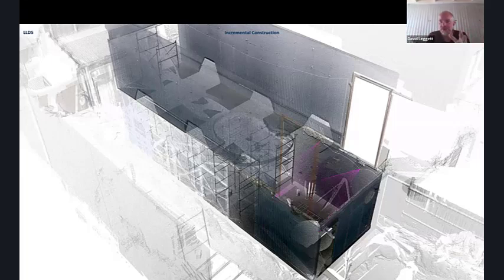after the core we found that the wall was out, particularly at the west end, by about 20 mil. So as I discussed before, because we had a parametric model, we could adjust the model to where the concrete wall locations are, and then everything else just got updated automatically before the fabrication commenced.